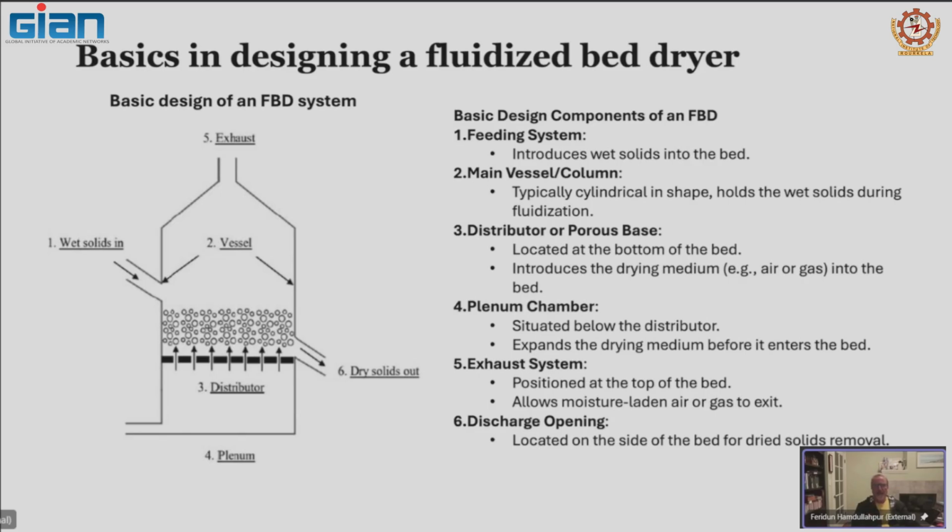Then you will design your exhaust system, ensuring that, again, for example, the slope of this cone, if you do it in this fashion, is important. What kind of angle you will use, and the exit losses here, we take into account. And if you need to control it two ways, you may want to put an exhaust fan in there, but usually you won't need it.